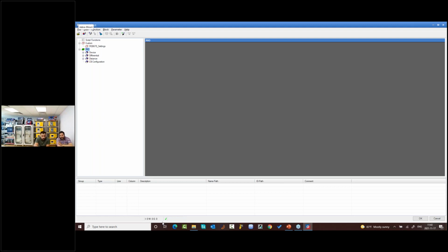Once you are dealing with our BTL and you're trying to import the relay setting, here there are 3 words and 3 numbers. I means imported, W means warning, E means error. So I import, for example, 500 parameters, and I have 1 warning, but I don't have an error, so it means it's fine. But here, because I'm not importing, it's 0. So it is 0 and 0 and 0. And since Ibrahim did the compiling and everything is fine, he doesn't have any problem.